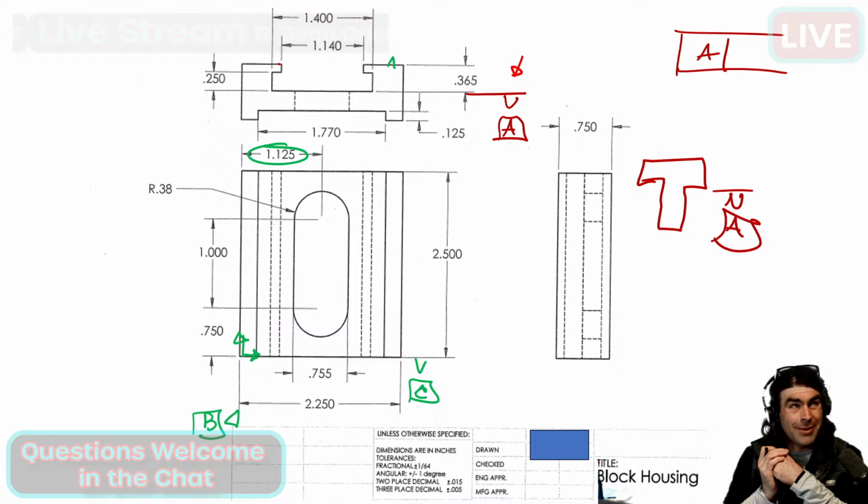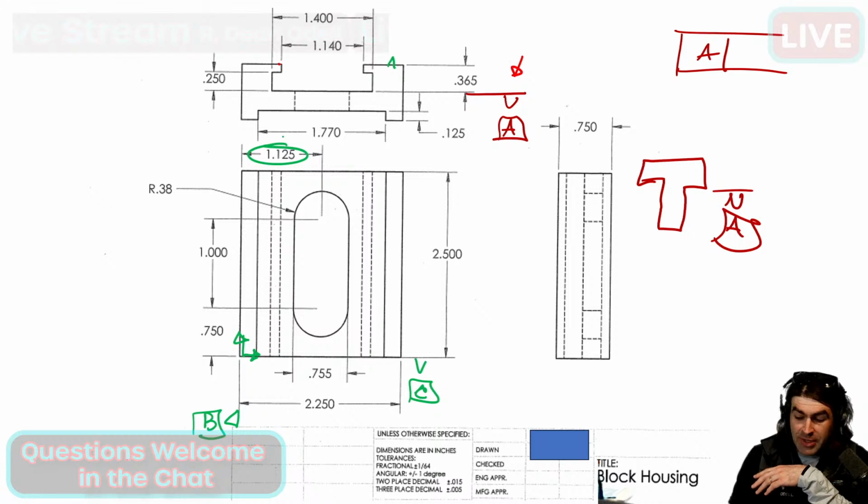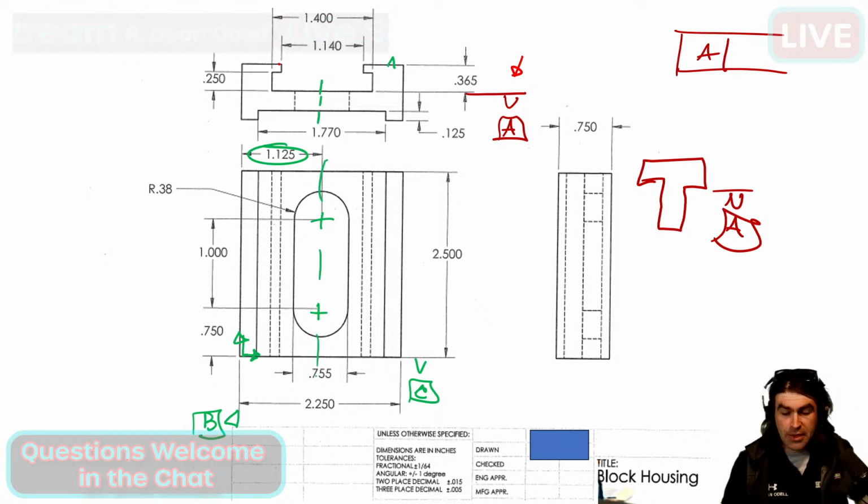This is the kind of problem you run into in CMM metrology: they might put one datum reference frame on there, but all the dimensions come from a different datum reference frame, right? If they're basic dimensions, it means the same thing. Shouldn't matter, but you never know what you're going to get. Again, this should have center marks at the very least. I'd probably put a center line here and a center line going down the middle of the part.